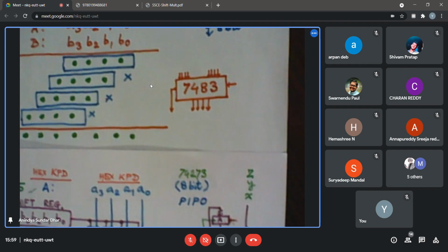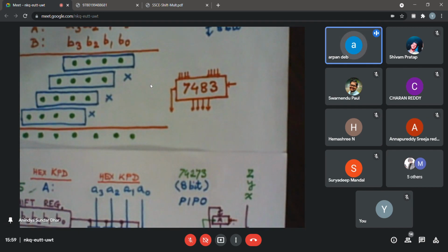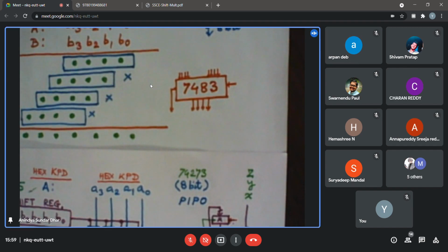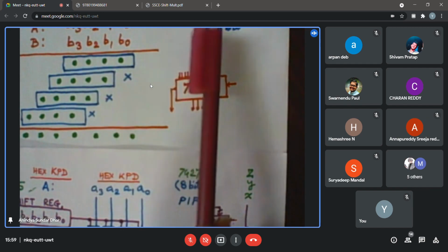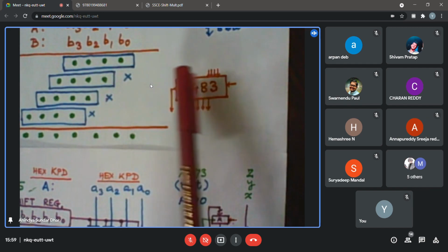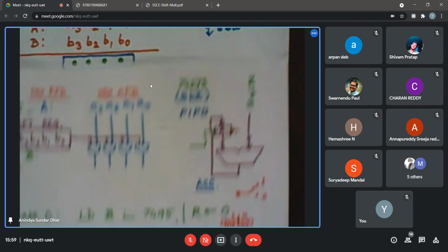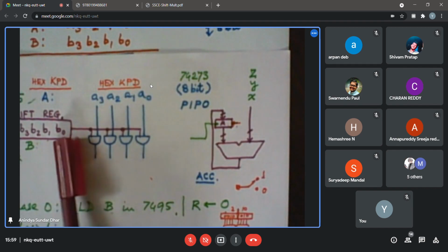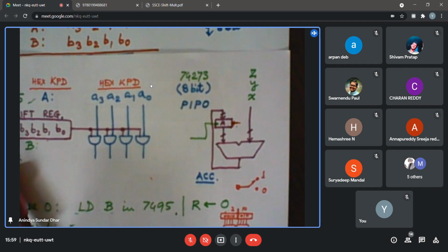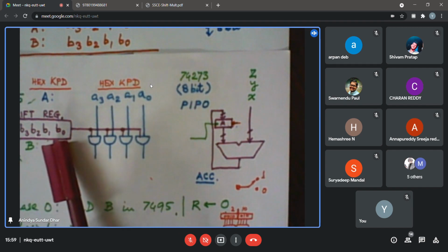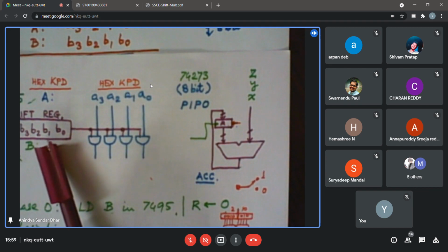Sir, we can also connect logic displays to the 8-bit output, right? Whatever you feel for your debugging purpose. But it is advisable that in the intermediate step you also check that after resetting, the content is shown to be 0. Because there may be a problem in the reset mechanism itself, or you may find sometimes that the shift register has not loaded the values at all because of absence of clock pulse or improper usage of load signal.